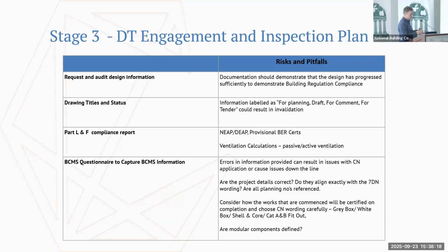If you're driving secant piles with the intention then of digging out afterwards, in some cases the piling itself can be the trigger for the commencement notice, and again, not the bulk dig or the foundations. The logic being if those secant piles are actually supporting your superstructure, then they're effectively permanent works, even though at that stage they're there as a temporary works solution to facilitate the bulk dig. So having these conversations early will help de-risk everything.